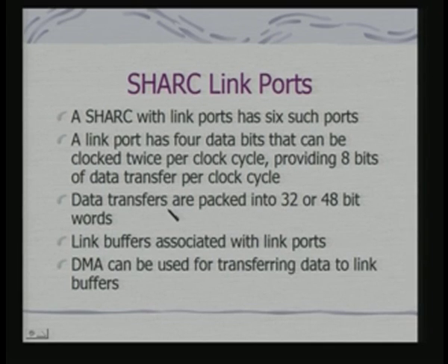These transfers are packed into 32 or 48 bit words. Each link port is associated with link buffers, which contain the data to be transmitted, and you can use DMA to transfer the data to and from the link buffers.